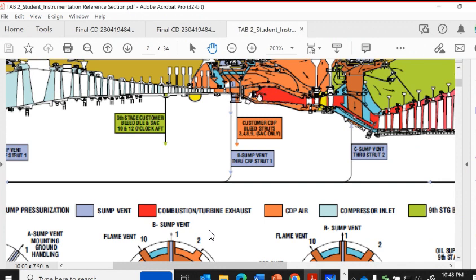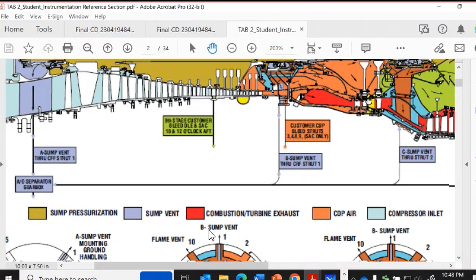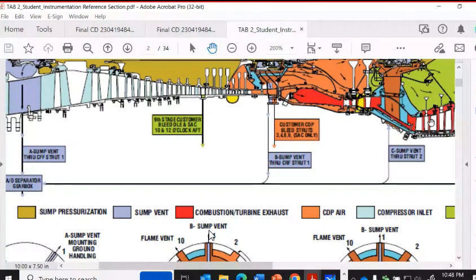And that tells me that, hey, I need this much fuel to maintain combustion and the speed of my high pressure turbine, and the output capability to push the power turbine. So this is what's going to be handled when we look at the fuel system, looking at the metering of what's going on in the turbine itself.